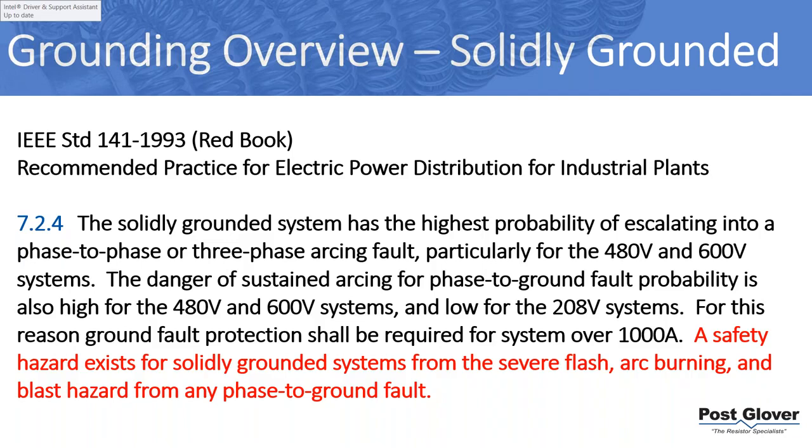Your relay system, your ability to shut down is typically not that fast. Potentially you could spend a lot of money, get some photo sensors, some pressure sensors, and do very high speed disconnecting, etc. And then people can do that. It's a high cost and high maintenance, but it's possible. But typically, almost all systems don't have that capability. And so therefore, arc flash is a big issue.